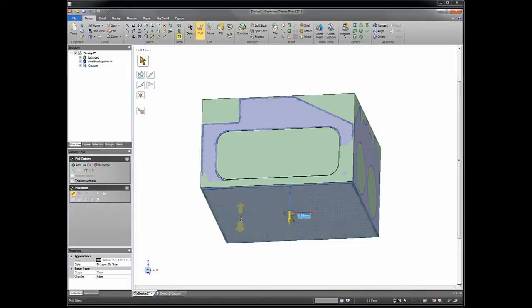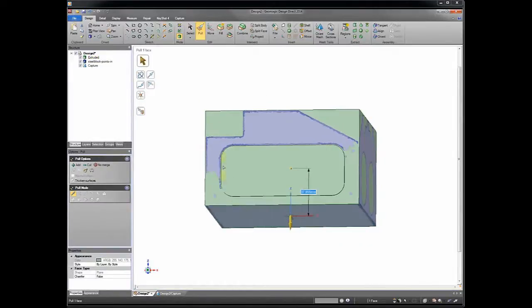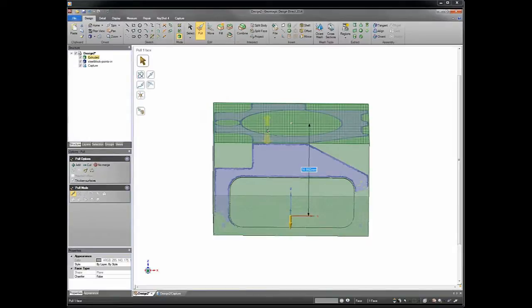Again, you can eyeball it, or you can pick a point on the bottom of the mesh, or what might be wise is to measure it. I want it to be perfectly offset from that top surface. So I click and it says currently it's 74.992. Well, guess what? I'm pretty certain the design intent was 75 millimeters. It's probably how this machine block was created. So it's not an exact science.